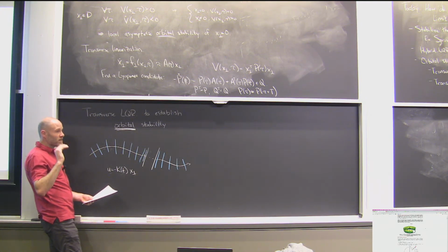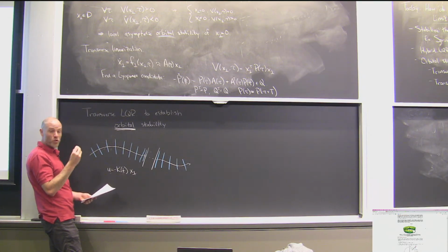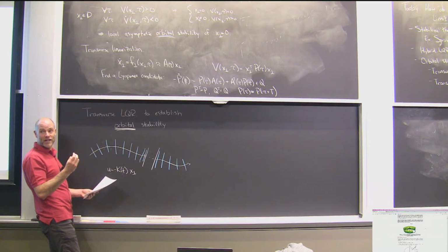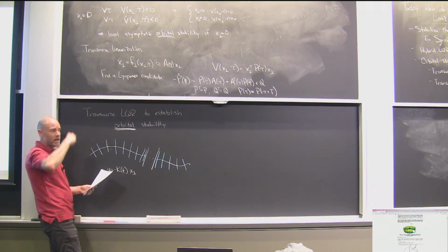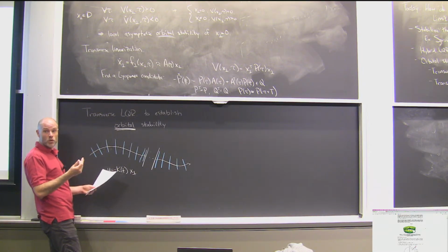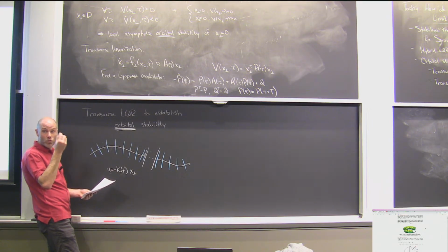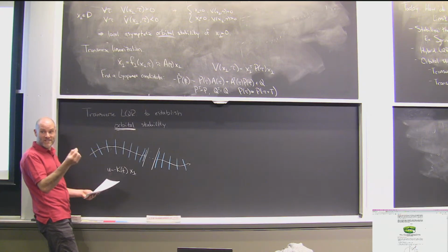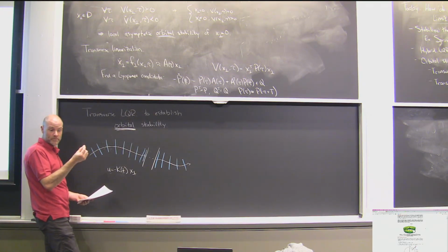If you find the time-varying LQR for the compass gait in the full coordinates, it'll tell you there's an extremely high cost to go and requires large actuation, or it might even be unbounded. But in the transverse coordinates, it's very well behaved. You're not asking this one actuator to try to catch up in time, which it just can't do. You're asking it to stabilize one less dimension.